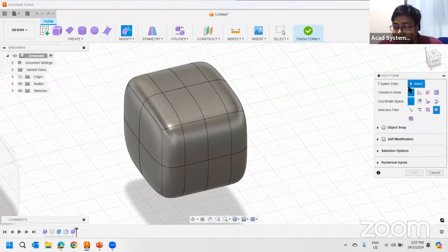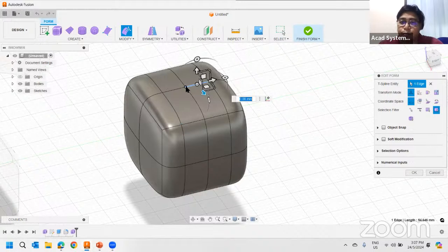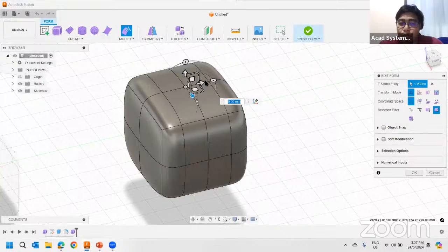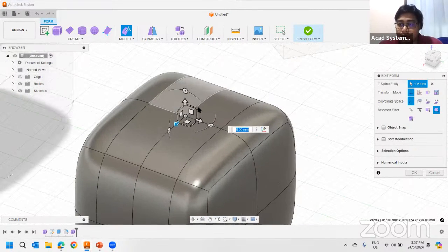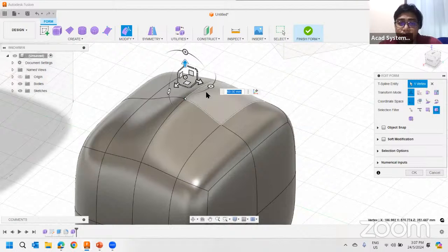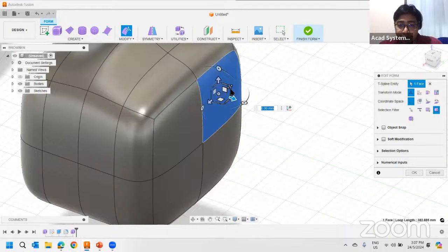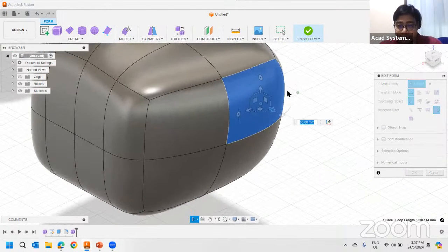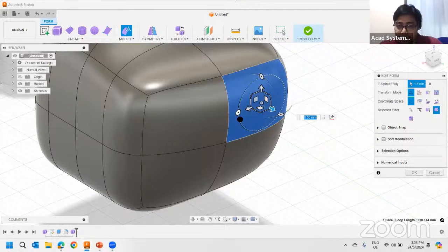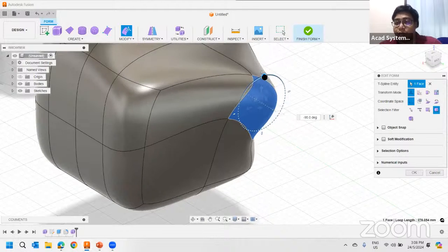And then the first one allows me to select the faces, or I can also select the edge, or I can also directly just select point only. And this point will pop out this gizmo button, right? Or this transformation button here. And this allows me to manipulate the shape here by using this arrow here. So I can just move it around. Maybe I want to select this face here. I can pull this one up. I can rotate it if I want to by using this rotate button here. So that is some form that we can do from here.